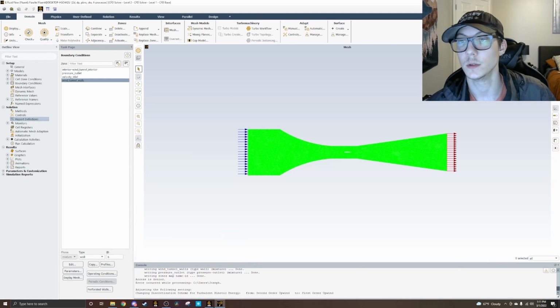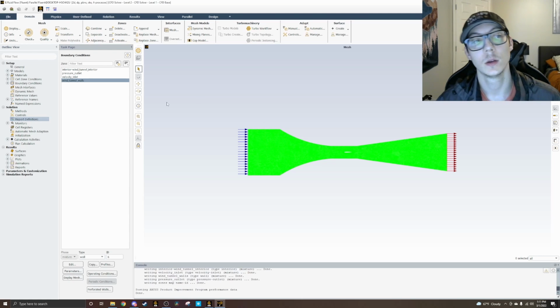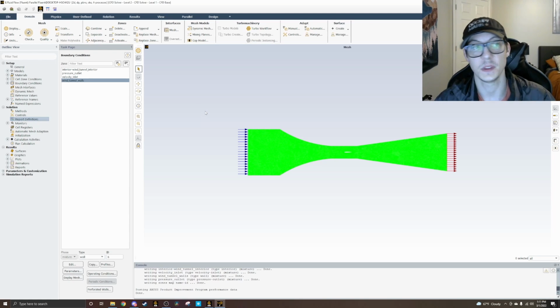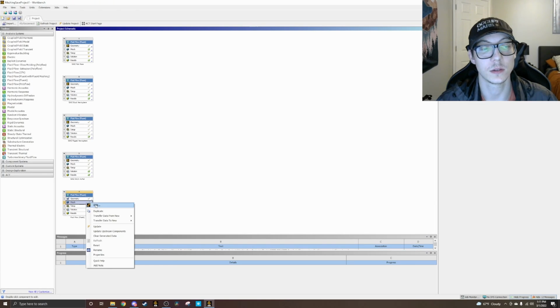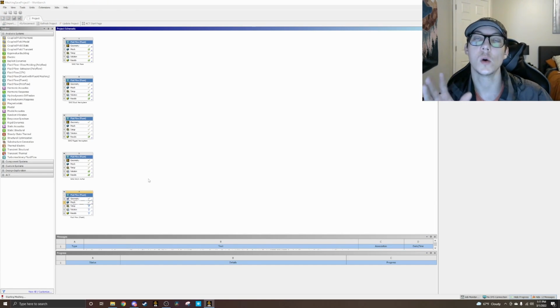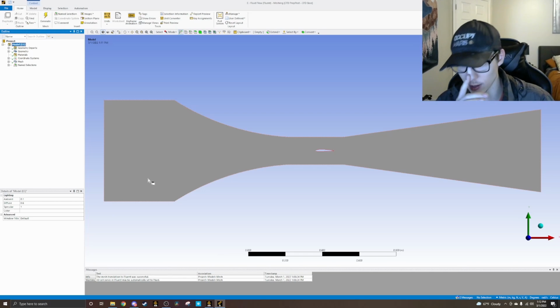So this is what we're going to do. This is an easy mistake that we can fix. So we're going to go back. We can just exit out of this. It should all save. We're going to go back and actually edit our mesh because we don't want to incorporate the NACA airfoil into the wind tunnel walls, because I don't want the wind tunnel walls affecting my coefficient of drag and force of drag.